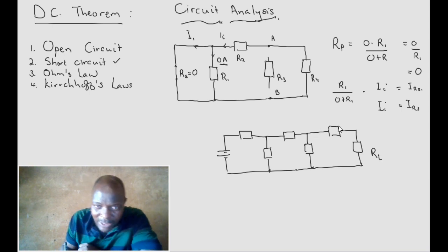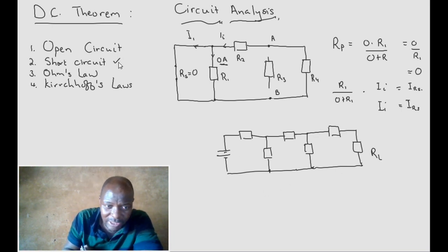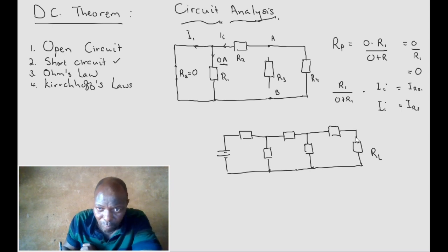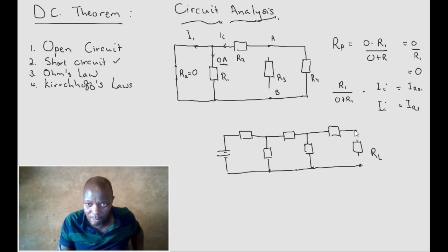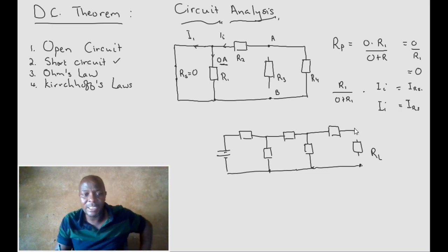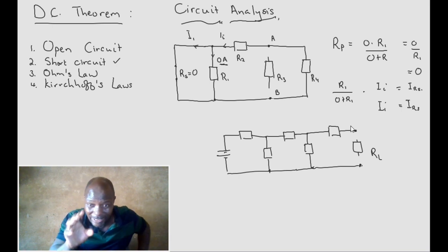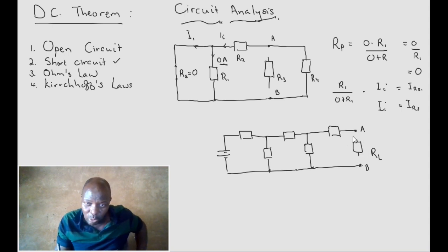Now, when you're doing resistance for Norton and for Thevenin, we would remove the load. Having removed the load, that is our point of connection for the load. Then we analyze the whole circuit and ask what it supplies at these points in terms of voltage and resistance looking into those points, at points A, B. So this is an open circuit. The result is that no current could flow. Current only flows through a closed circuit.